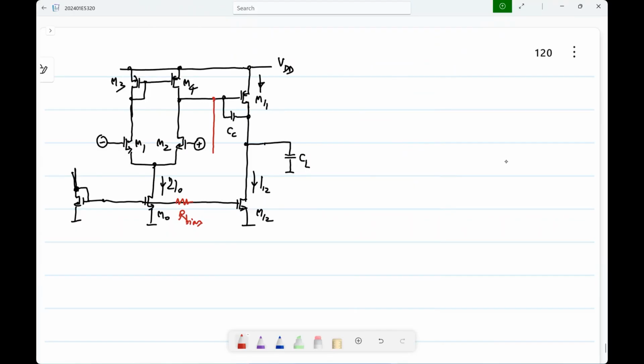So now the operating point is the same as before, right? Nothing has changed. Only thing is, the signal is also connected there, so that if you have an AC signal swing, the same signal appears there. Okay. And of course, you have to obey all the rules of AC coupling. That is, you have to make R bias times Cx large enough so that this network works for your signal frequencies. It will for sure not work for DC, and even getting it to work for very low frequencies may be difficult, meaning you may need very large R bias and Cx, which may give you other problems. Okay.